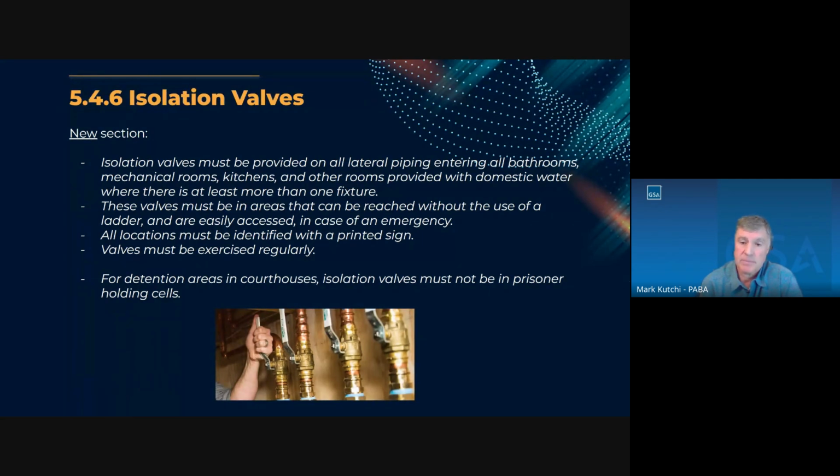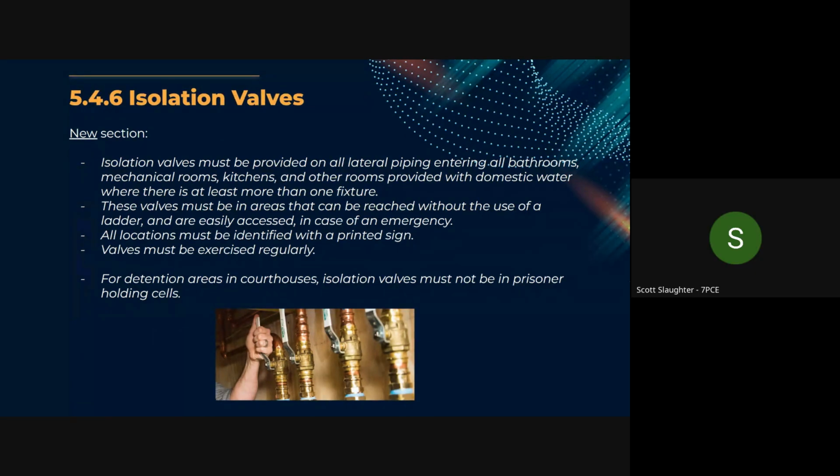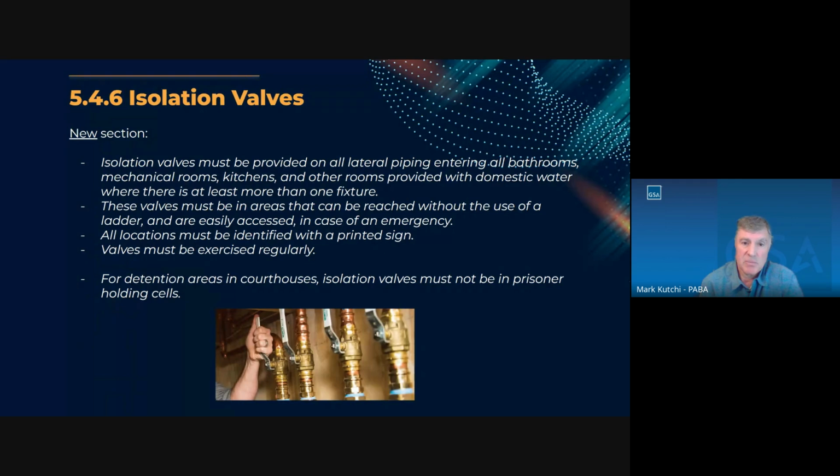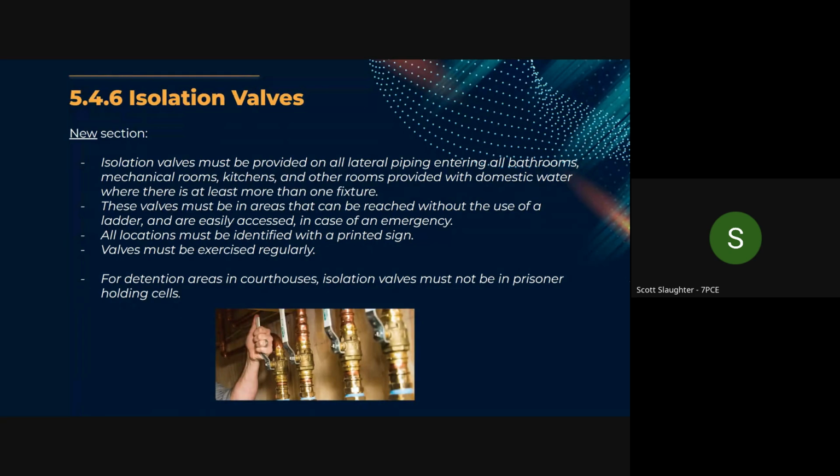Go ahead, Scott. You said more than one or one fixture, but is it more than one or just one fixture? Where there is at least more than one fixture. So two fixtures in a room, then we need an isolation valve. Yes. Got it. Thanks.